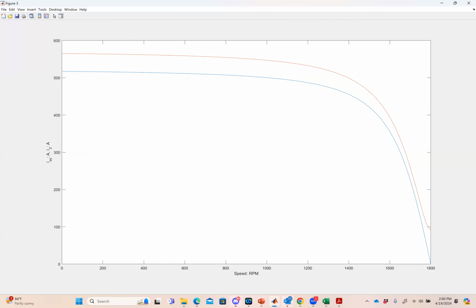All right, so the other thing I noticed, where did I say this machine was operating? Well, it was 1773 RPM. So let's go here. Let's get my pointer. So it's 1773 RPM. It's somewhere around here. Close enough. You can tell how steep the curve is here. At 1773 RPM, this guy looks like he's around about 66 amps. That would be what I would call his full load amps.